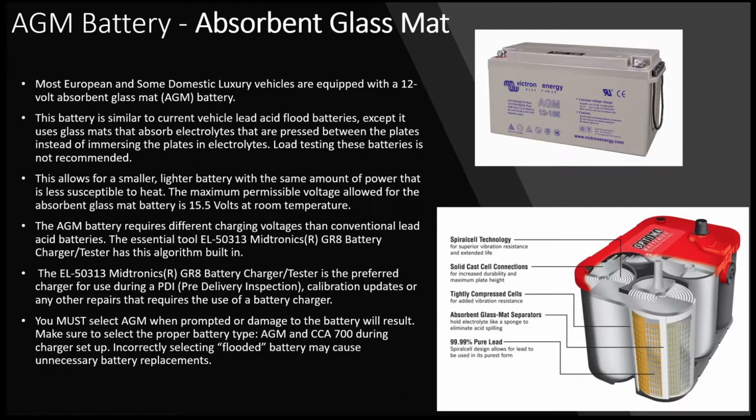This fiberglass mat wraps around it or is set side by side to it in a square battery like you see here. Right here, it's plates that are set side by side, but there are little pockets inside the plates, or inside the matting, that hold the acid. The same thing goes for these spirals. The nice thing about AGM batteries is they can be turned sideways, upside down, laid on their back or on their fronts, in any direction. They don't gas off nearly as badly as the SLI by any means.